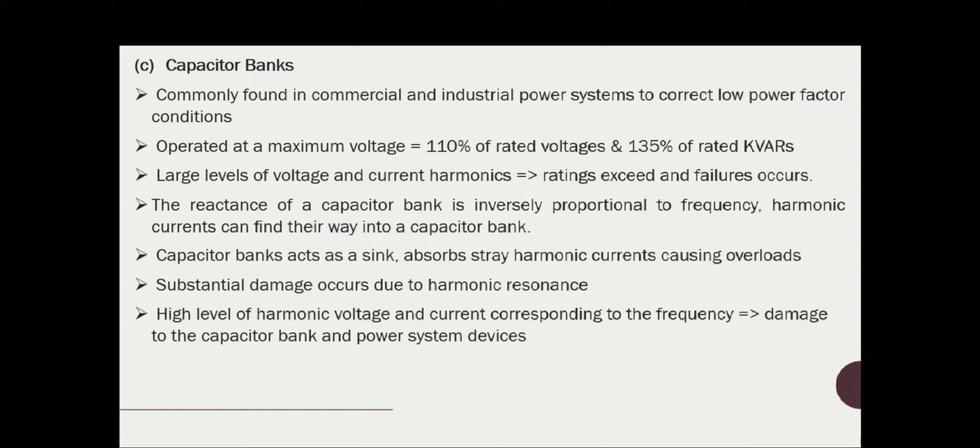There is also a more serious condition, with the potential for substantial damage, due to a phenomenon called harmonic resonance in the capacitor bank. Resonance conditions are created when the inductive and capacitive reactance become equal at one of the harmonic frequencies. At any one harmonic frequency, if capacitive and inductive reactance are equal, the resonance condition occurs and will damage the capacitor bank. That is a more severe condition. There are two types of resonance, as you all know, series and parallel resonance. In general, series resonance produces voltage amplification and parallel resonance results in current multiplication. So there is a possibility of harmonic resonance in a capacitor bank with the presence of harmonics.